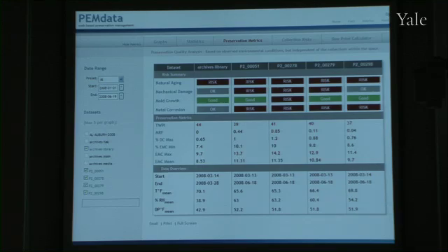If you want a little bit more nuanced understanding of how good or bad the environment is with respect to these things that are critical to collections care, then you look at these numbers, which we call the preservation metrics. These numbers are derived from the raw temperature and humidity data. I'm not going to explain them in detail, but that one relates to chemical aging. It's very important for fading of dyes and degradation of paper. That's a factor that tells you whether mold would be possible, and when it's in red, it says, pay attention to me. These particular spaces are all problematic from the natural aging point of view.